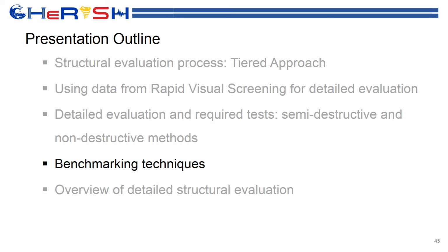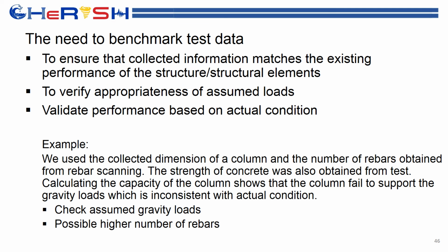Okay, so now I would like to talk about the benchmarking techniques. And why do we need benchmarking techniques? Well, we need to benchmark the test data because we need to ensure that the collected information from the test matches the existing performance of the structure and the structural elements.